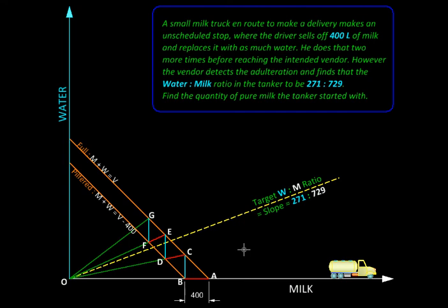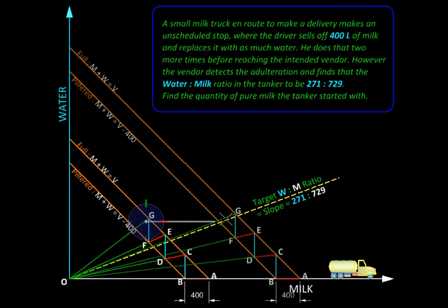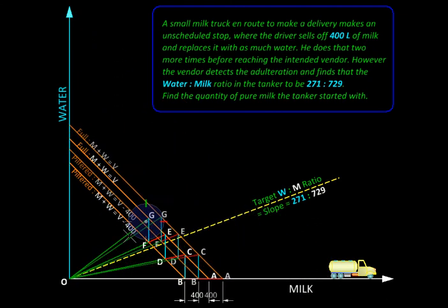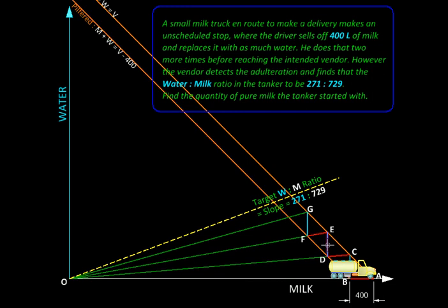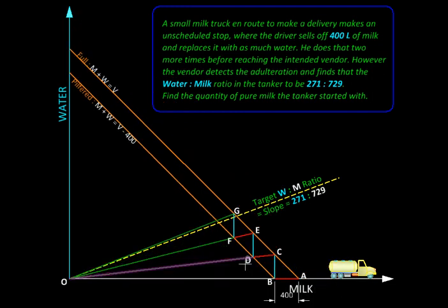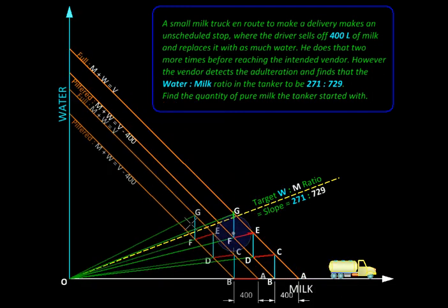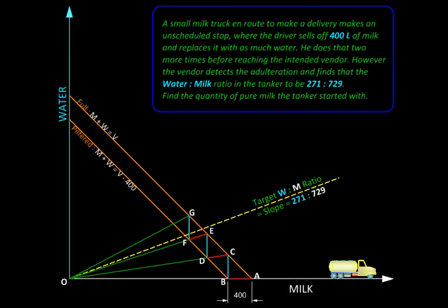Parametric geometry is called dimension driven design in MicroStation, and it allows us to take a geometric diagram like this and move it any which way we want while retaining selectively certain relationships. For example, suppose I take this diagram and move it here. But I have kept these two lines parallel to each other and the distance between them in the horizontal direction to be 400. Now that is not going to change wherever I move this diagram to. So that is the power of parametric geometry or dimension driven design.